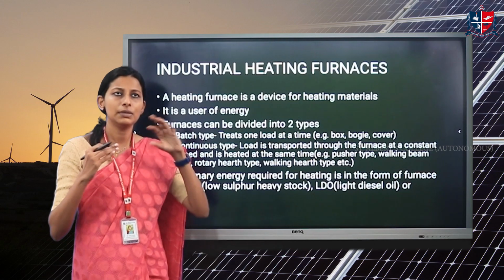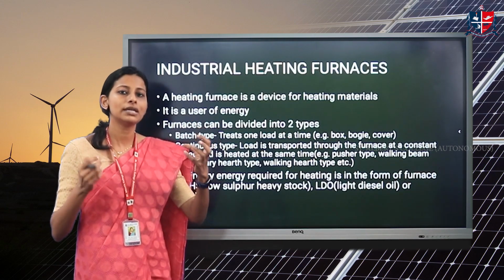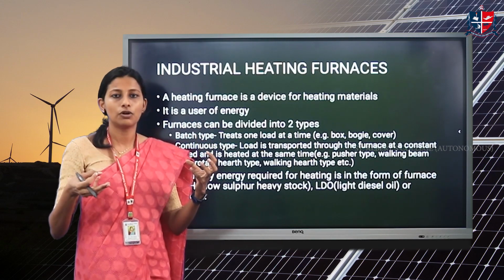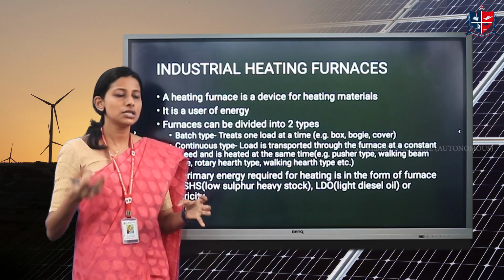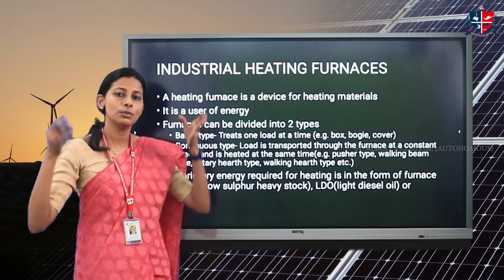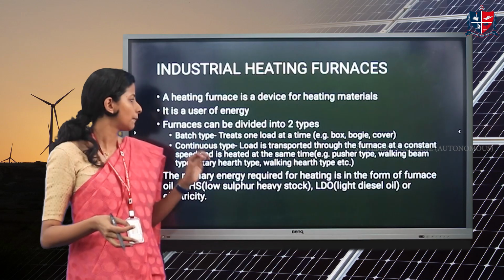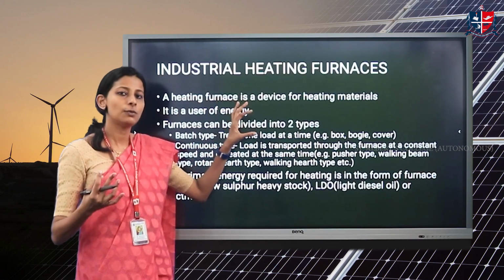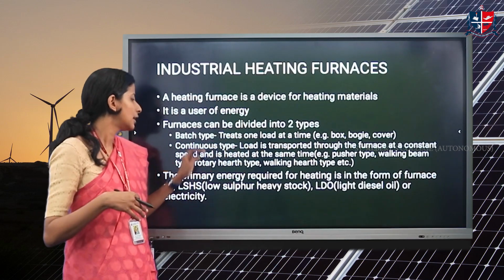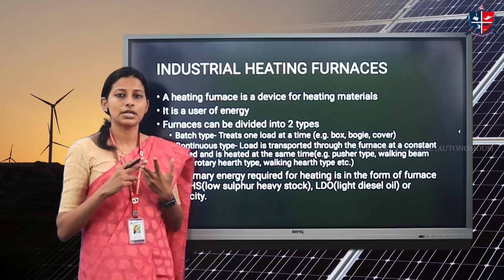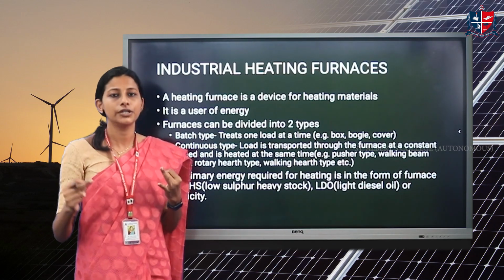Many manufacturers require things in a heated or molten form, or maybe even in gaseous form. Such things can only be generated by heating in a very large piece of equipment called a furnace. So the basic definition: it is any device that is used for heating materials. Broadly, they are classified into two types. One is the batch type, and the other is the continuous type.